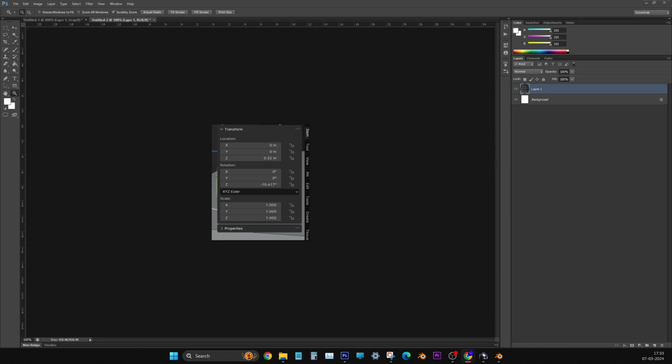Yeah, in the same place, two vertices are there. We have to make it one. But it will show you one when you press M on the keyboard and merge by distance. It will show you the count that I have merged two vertices, now it is only one vertex. From the two vertices only one vertex is remaining. Like that the count it is showing. I wanted to show you that so that you will follow the same thing when you are doing these things.